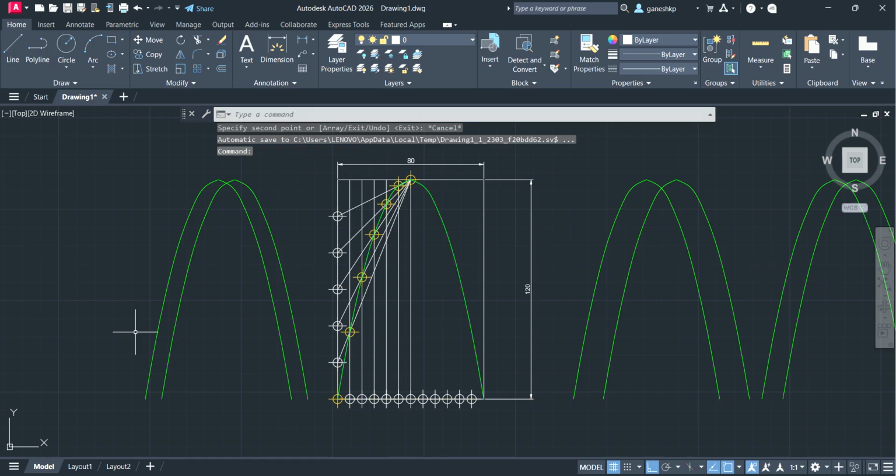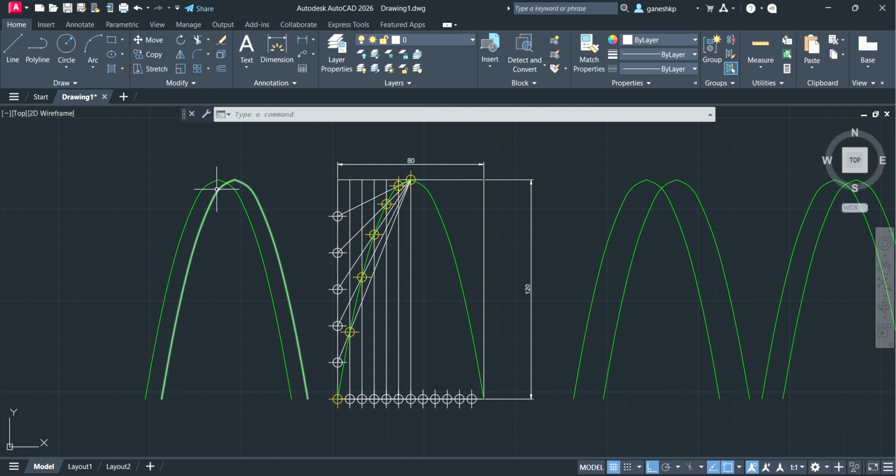Okay. So now just look at the copy and move commands. If you want to create a number of the same components, you can use the copy command. Suppose you do not need a number of objects, you simply move from one place to another place, then you can use the move command. Suppose if you want to delete the object, just simply select the object, delete it.